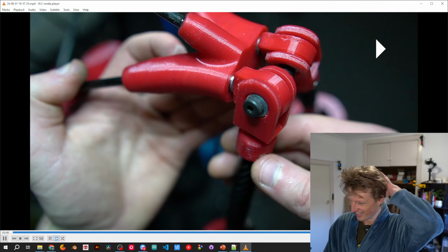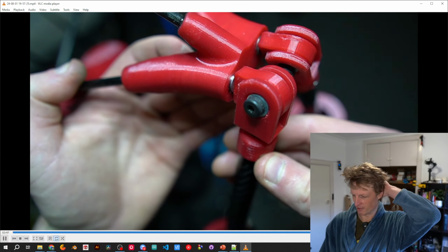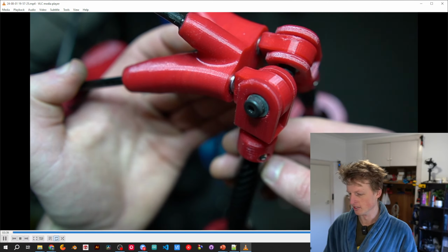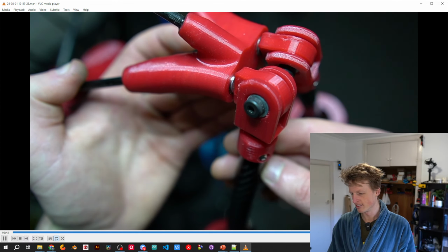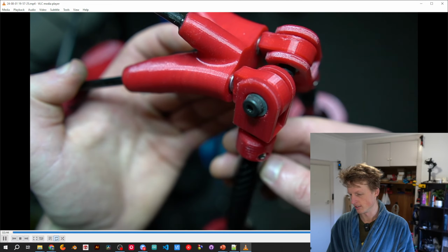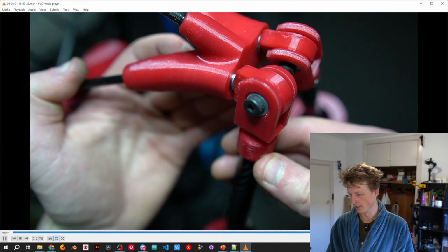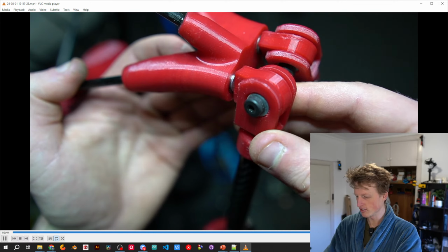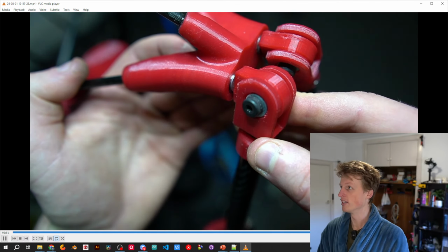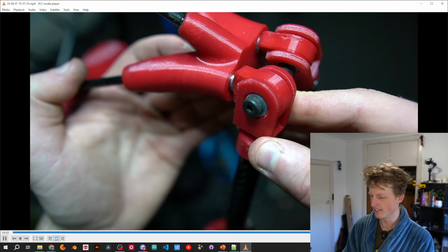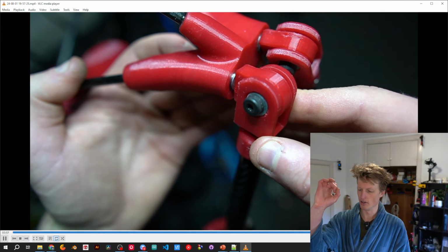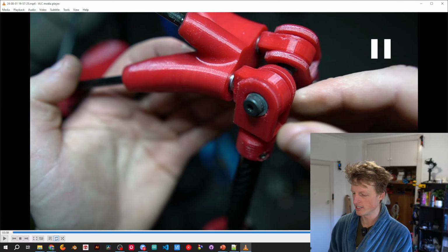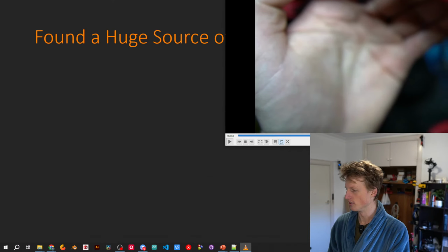So you can see, it's kind of hard to get this on camera, but there's quite a bit of slop in and out, as well as up and down, if I move over to doing that. You can probably kind of see it there, but the problem is the bearings are not perfectly well seated in the little hole they're in in the printed part.